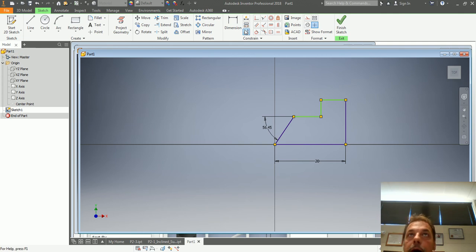Sometimes you hit show constraints. Notice that it's already got a perpendicular constraint. These are geometrics. It's got one there, one there, one there, one there. So that's why it's not letting me actually do a parallel from here to here. Look, that one right there says it's grounded because I started from this point right here with this first line. Okay, I'm going to turn these off for a second, or you can click on it and delete that one if you wanted to. If I wanted to, right click, hide all constraints, we're going to hide them all.